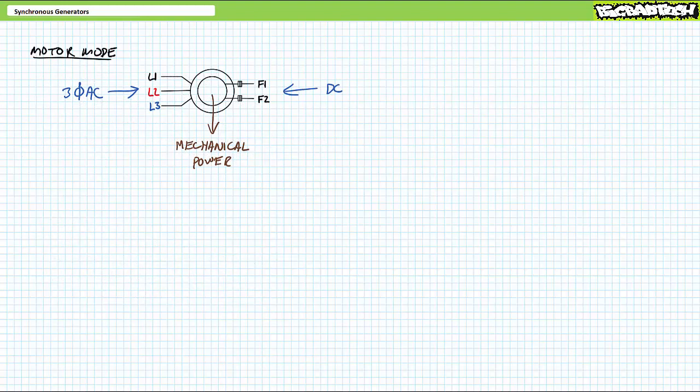Let us briefly review the parts of a synchronous machine. As you are no doubt aware, an electrically excited synchronous machine consists of three electrically isolated windings in the stator in a Y or a delta configuration and a DC field winding on the rotor. The rotor field winding is accessible via a set of slip rings which maintain electrical connection regardless of rotational position to a stationary DC source known as an exciter.